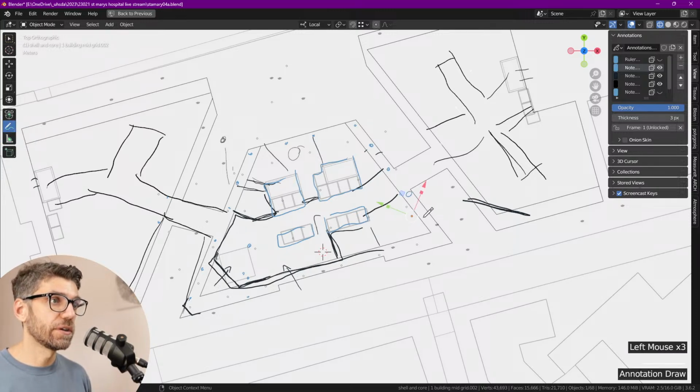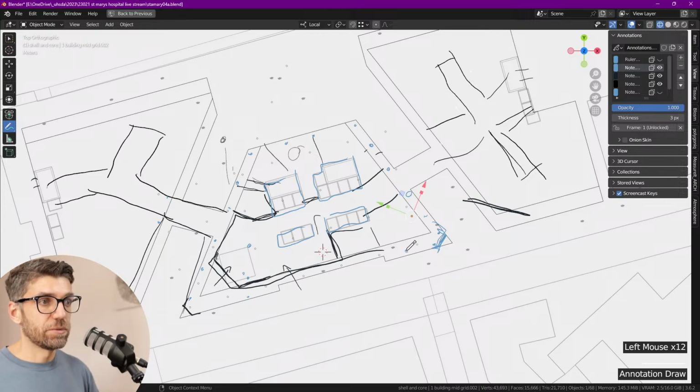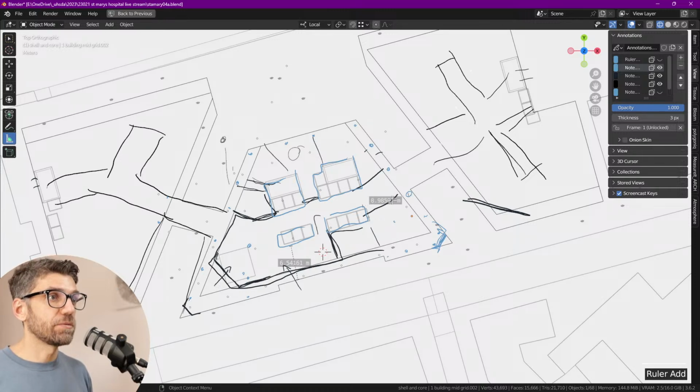Got a column there, column here. Again, this is going to get cut back to something like somewhere over there. We have a column there, column here, somewhere over here, there. We're going to need the middle column for sure in this space over there. And I just want to check what this span is. 8.9. So that's pushing it, right? That's a pretty close maximum.